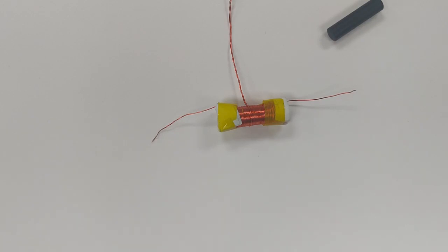And so in this next part, the tuning part, we're just going to show how varying these components, changing their inductance and changing the capacitance, changes the resonant frequency. So it's pretty simple. We're going to be using the Fourier transform function to demonstrate that. After that, we're going to take a break from the inductor and create a modulated signal. So we're going to be using the signal generator to create this pseudo carrier wave, and then modulating it and then demodulating it, so that we can see what a demodulated wave looks like.